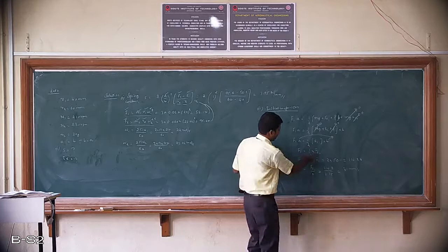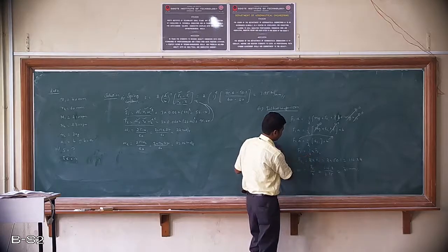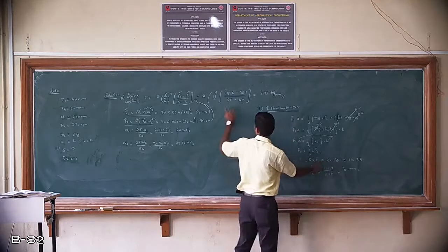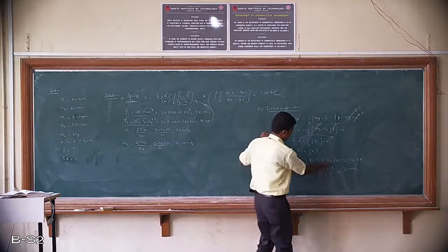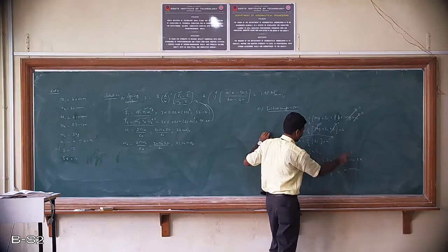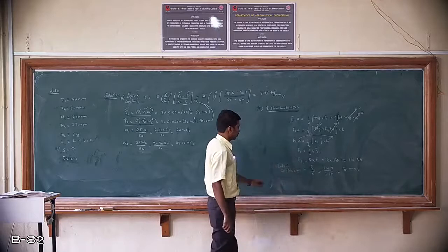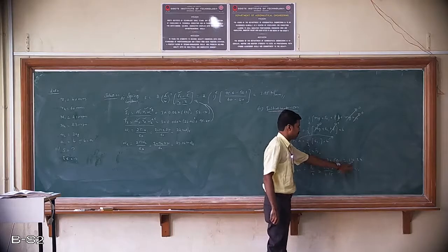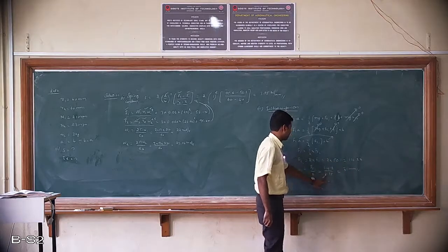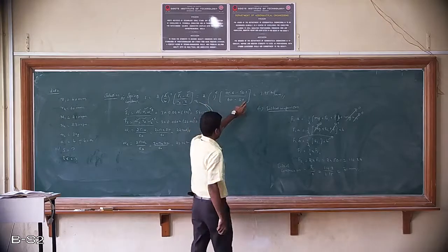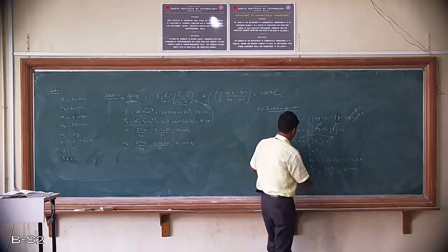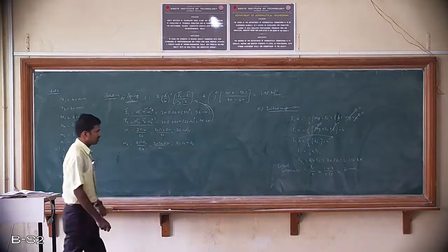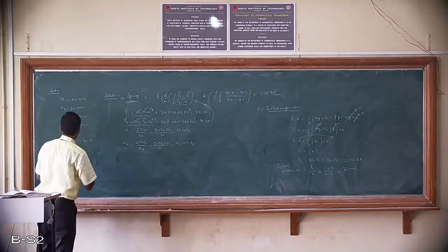So I need to get the value of Fs1, so multiply 2 to this side, so it becomes Fs1 is equal to 2 into F1. So 2 into F1 value is already known, that is 58.1. So substitute, you are going to get the value of Fs1 as 116.2 Newton. So the final equation for initial compression is given by Fs1 by S. Fs1 we have calculated, that is 116.2 divided by the spring constant S we have calculated, that is 3.75. So you get the value for initial compression as 31 mm. So this completes the problem number 1. Next, let us discuss the problem number 2.